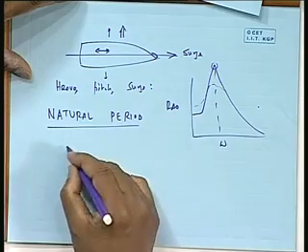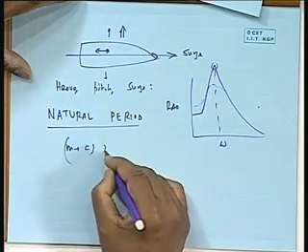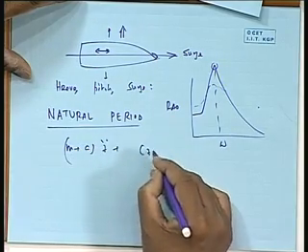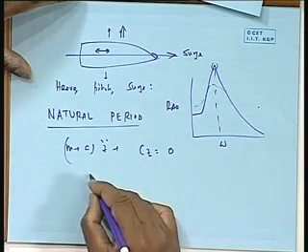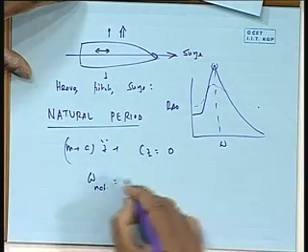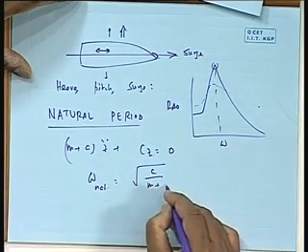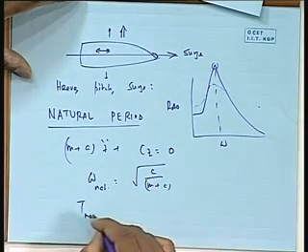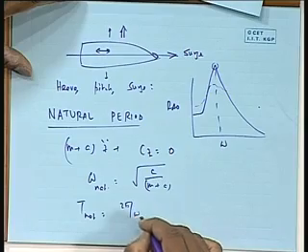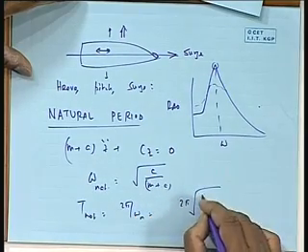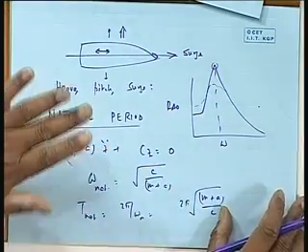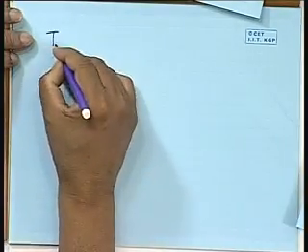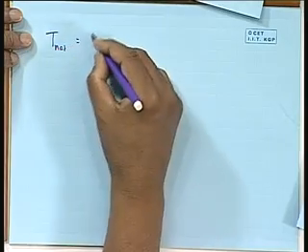The formula for that is given by, if you go by this equation, setting this equal to 0, omega natural is given by root over of c by m plus a, or T natural is 2 pi by omega natural, equal to 2 pi root over of m plus a by c. I mentioned that, but I want to right now discuss a little bit about the natural period values approximately.